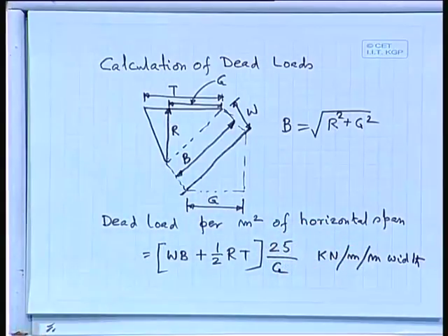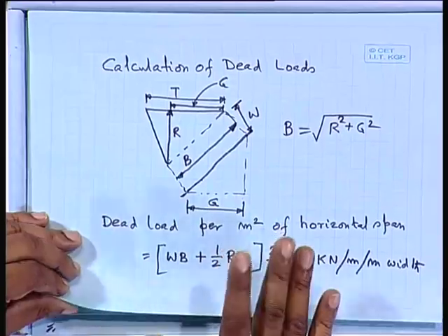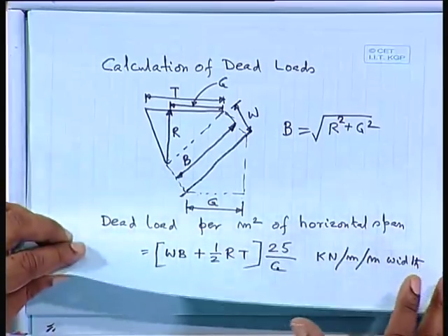So, what is the difference between slab and beam? Slab means we shall provide the reinforcement only due to bending moment and shear force, whatever it is, and we shall design it in such a way that we increase the depth so that we need not provide any stirrup, any shear reinforcement. So, then we shall call it a slab. But if we provide stirrups, that means we are designing a beam. So, in our case here we shall design it as a slab, because we are not going to provide any shear reinforcement.